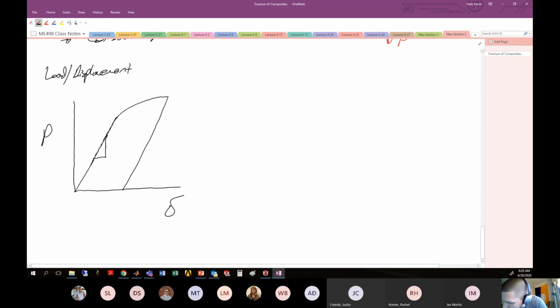So here's your elastic modulus E, and we're also unloading with that same elastic character E, and we're loading up here. Here's our yield point, and this is generally how the material will behave. It reaches some maximum value of load and displacement. Let's say that this is point A, and it's got maximum displacement here, delta final, and it's got maximum load here, P final. So these are like your XY coordinates of this particular point, right?